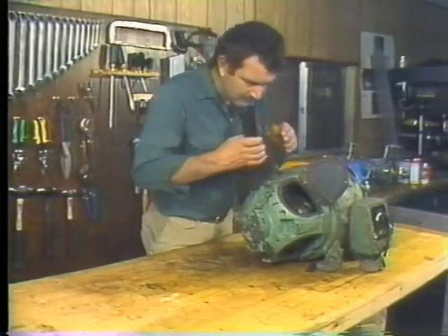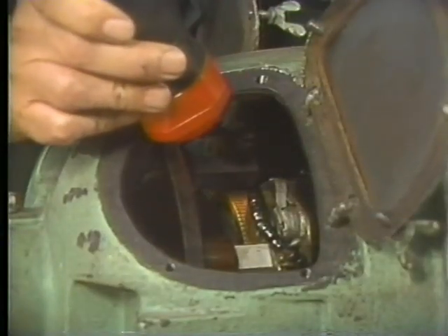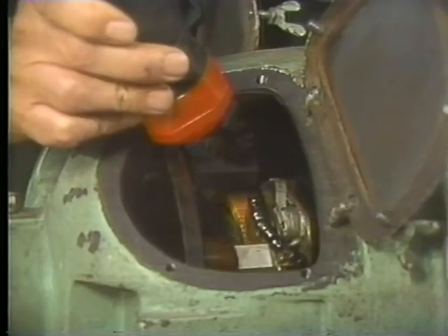It's not difficult to check. With a good light, you should be able to see whether or not the mica that insulates the copper segments from each other is okay. If the mica is clean, its color will be anywhere from light gray to white. If it isn't, dirt and other particles will show up as dark specks.